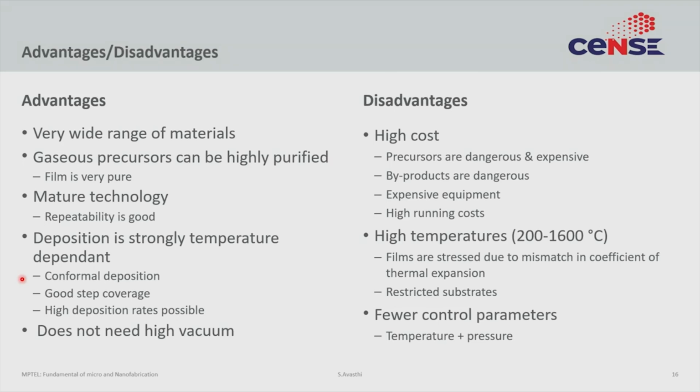the film, because once you deposit a film at those high temperatures and then you cool it down, it can have some residual stress, which can cause problems. This is especially important if your lattice is mismatched. This is especially important if the film that you are trying to grow on the substrate does not necessarily like to nucleate on the surface very well. We shall look into all these details a little bit later.